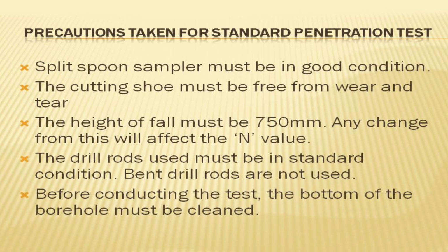Precautions taken for standard penetration test. Split spoon sampler must be in good condition. The cutting shoe must be free from wear and tear. The height of fall must be 750 mm. Any change from this will affect the N value. The drill rods used must be in standard condition. Bent drill rods are not used before conducting the test. The bottom of the borehole must be cleaned.